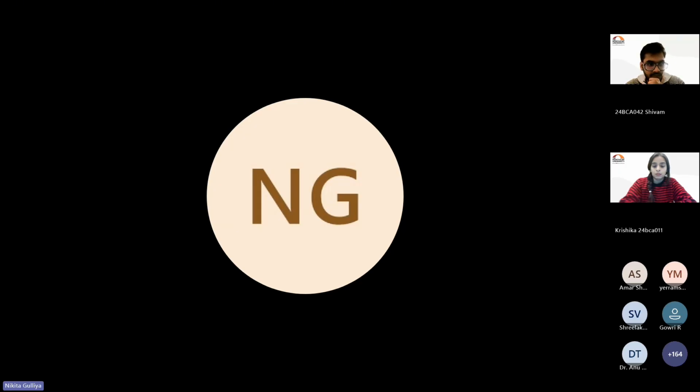So it is a virtual, software based environment where the RTL can be tested by giving negative and positive values and looking at the result through simulation. There are various simulators, like I mentioned, ModelSim or Questa Sim at the industry level, where you can check that it is following the protocol, following what I specified or not. Is the functionality which I wanted achieved or not?